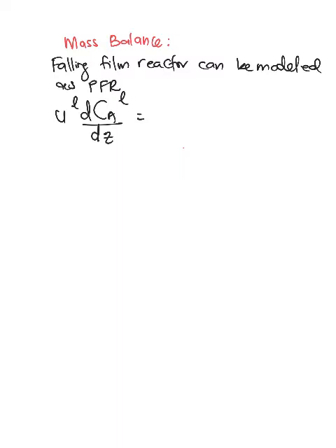So your overall mass balance becomes negative A over V, because of mass transfer of oxygen from the liquid to the external surface of catalyst. And we divide it by 2 because of the stoichiometry.